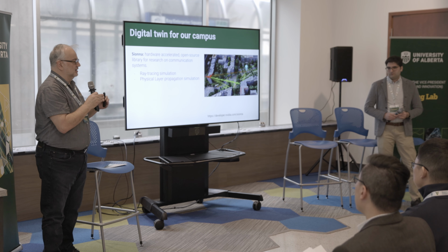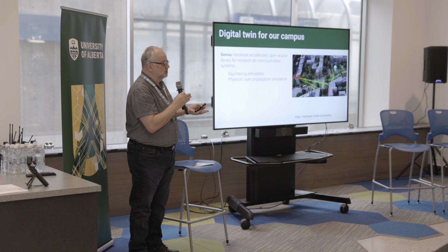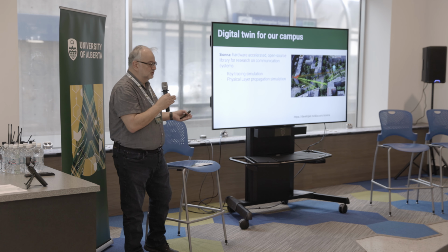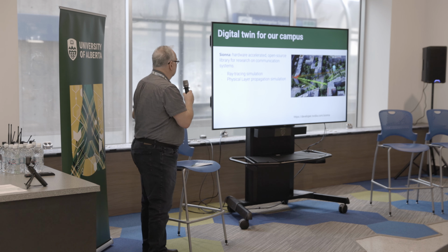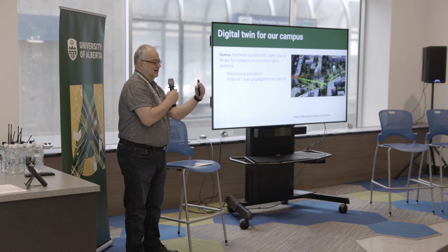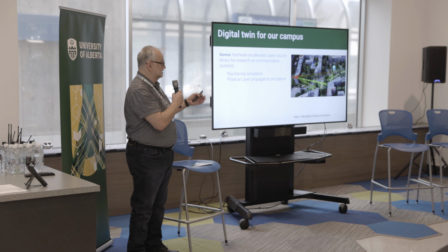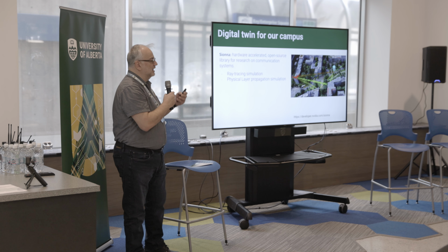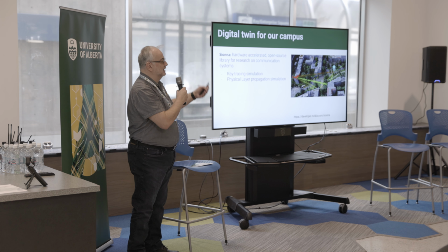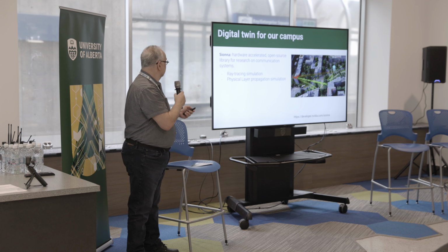Until relatively recently, the idea that you would have complete ray tracing models for the wireless propagation on a big campus or inside buildings was rather computationally prohibitive. So that's where tools like Sionna, which of course leverage the power of GPUs today, come into play. The aspects that are simulated here can then be matched to what we have measured in the real environment. And by aligning the two, we can then make predictions based on the simulated models. So the data collection side, which is labor intensive, can be mitigated. And then the quality of the results can also be tuned. If we want better quality results, better localization, we might actually engage in a more accurate simulation and surveying of the space.